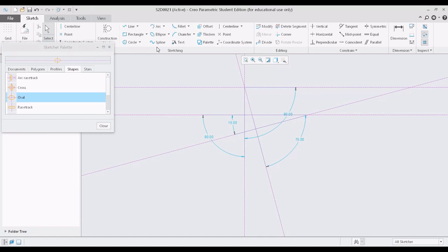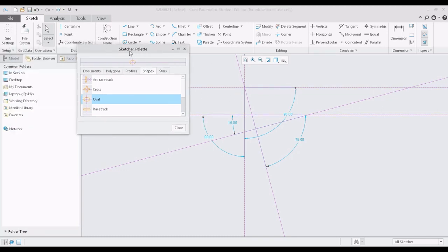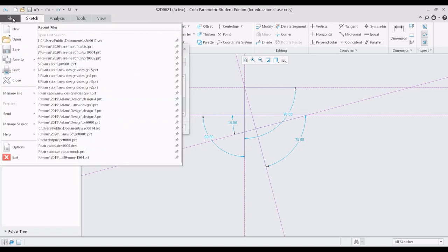We don't want to waste our time creating the aerofoil again and again at different locations of the wing, right? So what we need to do is create the aerofoil in the 2D sketching module, and save the sketch by clicking on file and save.